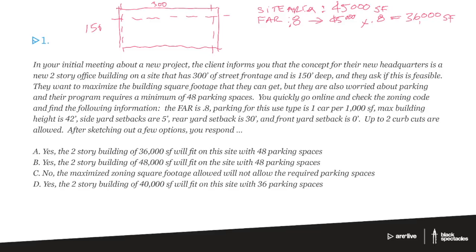It's a little weird, but it means that you can have an area district that can have very, very tall buildings by putting a FAR of, say, 10 or 15 or something like that, and that would allow you to build 15 times the site area in floor area. Or you might have a more single-family home residential area, and it maybe says FAR 0.5 or 0.3 or something. So you'd have very small amount of buildable area on the overall site. So that's just one way of thinking that stuff through. We need to know the site area first, then we have the FAR, now we know the buildable area that we're allowed. So that's an important number.